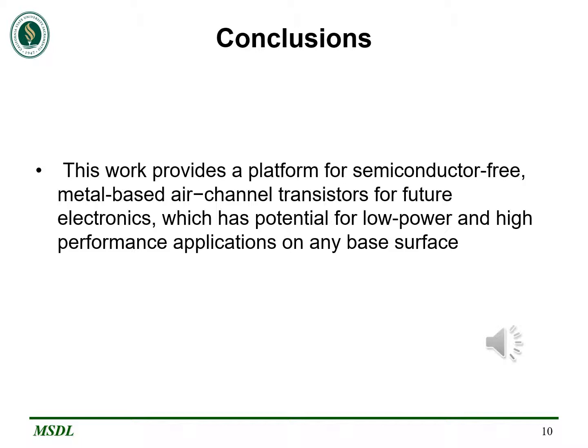All devices behave as bidirectional transistors due to the symmetric source-drain geometry. However, variation in the positive and negative bias operation is observed depending on the tunneling mechanism of electrons. Experimental data shows that Fowler-Nordheim tunneling is dominant in tungsten and gold, with Schottky emission only in platinum. Forward bias current is higher than the reverse bias current when the device experiences Fowler-Nordheim tunneling, while it is of the same magnitude for Schottky emission under the influence of gate voltage.